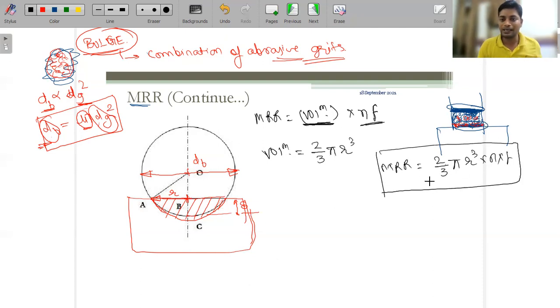Okay, now the same thing which we discussed last time, that these abrasive particles can be different in nature, meaning different in dimensions. So if here we are considering that the bulge contains 10 abrasive particles of different diameters, then the second time there is a possibility that it will be 8 grits only, and the next time like 12 grits. So it can increase or it can decrease. So for that we have to calculate the indentation, because if one bulge is coming in contact with the workpiece and removing material, we can say that this is the maximum we can consider.